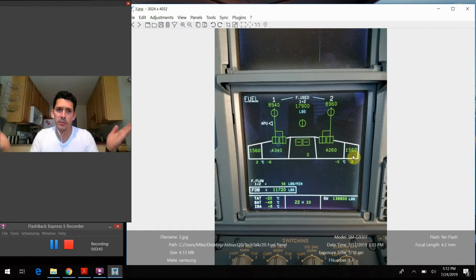As the plane is flying along, you have all these forces that are flexing the wings up and down, as part of a normal flight and turbulence. But these counterweights in the form of that fuel residing out towards the edge of the wings offset those forces a little bit. So once again, a really interesting design concept that they incorporated into the airplane.